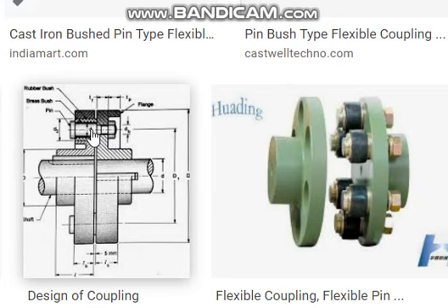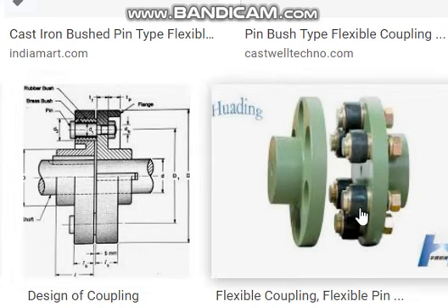Okay, and above this pin you have two bushes. One is a brass bush, another a rubber bush. You see inside, the rubber bush is seen, and below this the brass bush should be there. This permits a misalignment of maybe some 2 degrees or so.